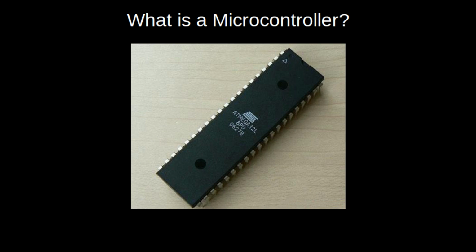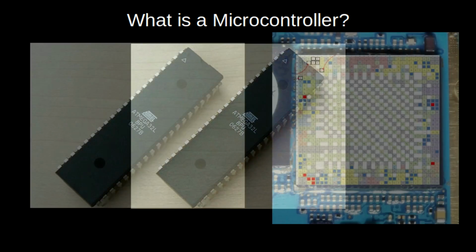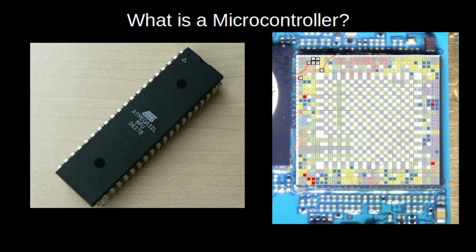Microcontrollers are different from larger computers or the system on a chip in your cell phone only because of their scale. They have lower processing capabilities, smaller amounts of memory, and much simpler I/O circuitry, but that also makes them comparatively inexpensive. Having all of these components integrated into a single package also makes them easier to use because you neither have to deal with building the support circuitry to interface memory to CPU to inputs and outputs, nor do you have to deal with the complex packages used for SoCs such as this.